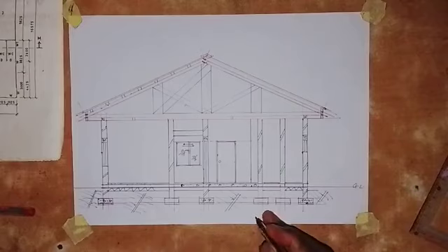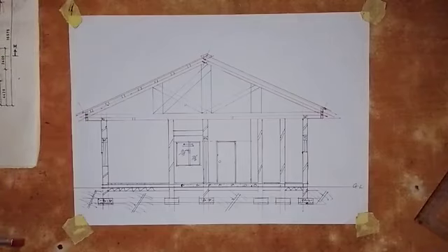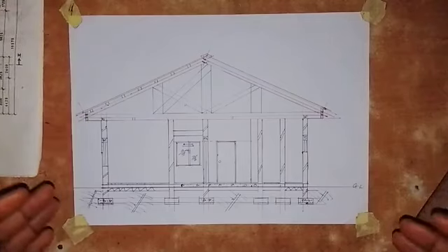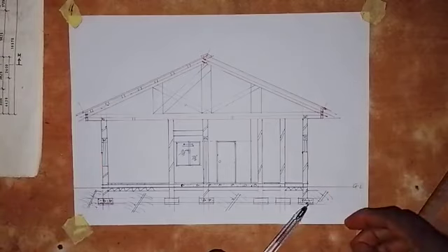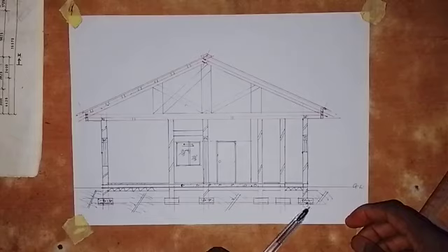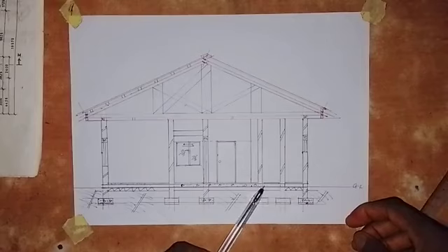Okay, so all we have to do is to write it here. So write sectional view and write the scale here. So just make sure you do that. After that, you are done with this work. Another thing is that if you can label some of the parts, what I mean is this. For this you can write blinding. Just draw a line and write blinding. And for this one, write foundation footing. And then for this, write hardcore. This is the concrete slab. This is the screed. You can write that.